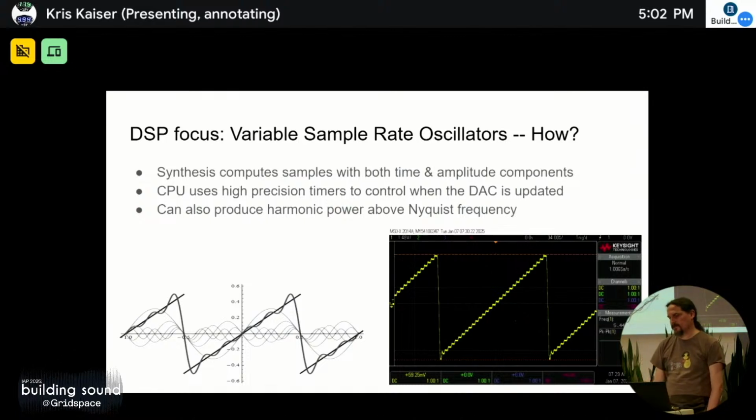Our original timing when this was first developed was about 100 millionth of a second. It was our sort of time base. And there's some latencies involved, but we can get pretty close to that as an accuracy for placing points, samples in time. The right is actually a scope capture of one of our oscillators that do this. There's actually 32 steps per waveform at that pitch.